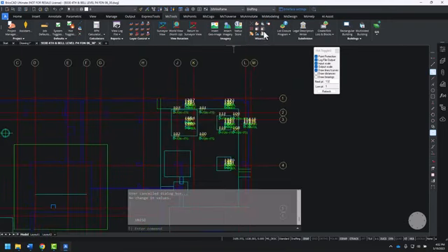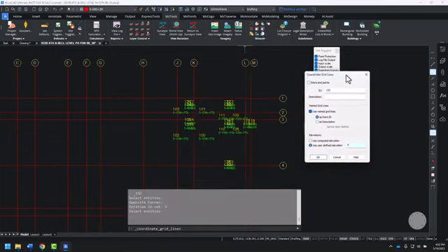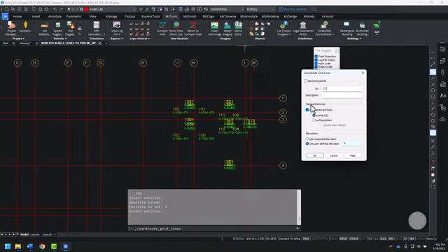And now I want to add points to the grid lines by using the Coordinate Grid Lines command. I'll isolate just the grid lines, and I'll create points on the grid lines using the Coordinate Grid Lines command. I'm using named grid lines, and I want to use named grid lines as the point ID. And I want to use a user-defined elevation of 0 for these points.